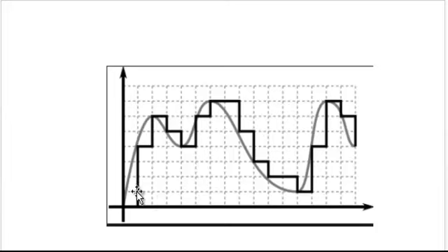See here. So this is the continuous time signal actually. So this is discretized with respect to time. This grid will represent the discretization with respect to time. And similarly here in the amplitude also, the signal is divided into different values. If you notice over here, this is our continuous signal. So here this value will be given to the nearest amplitude of this level.